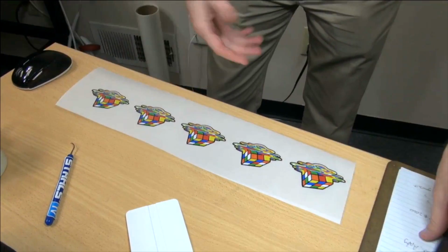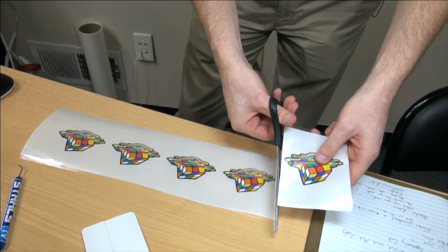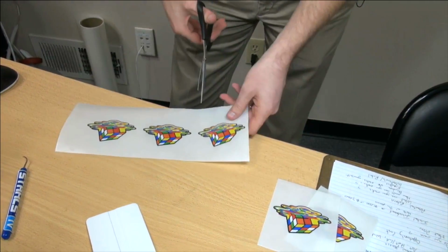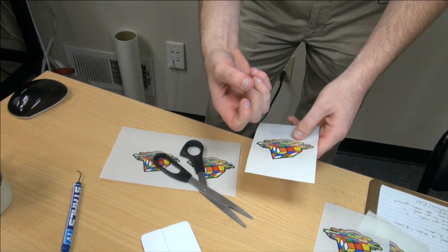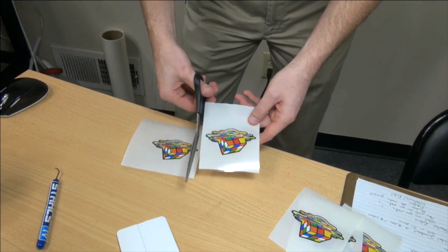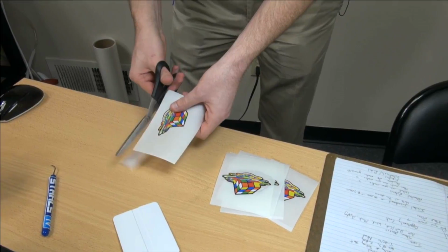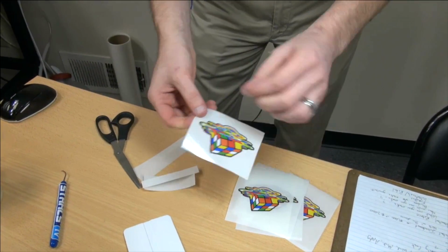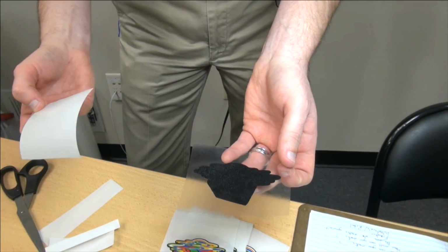All right, so now I can cut these apart. I can hang on to them for a few days if I want to use them later. Normally we get the question, how long can I let these sit? You don't want to leave them sit for weeks at a time, because what happens is the ink can actually migrate back into the mask, and the mask will lose its stickiness. So that's the risk of letting them sit for long periods of time. They can definitely sit for a week, 2, maybe even 3 weeks, but you probably wouldn't want to let them sit for any longer than a month. All right, so I'm just making this a little easier to grab, and then again, all we're doing is peeling off the backing, and we're ready to go to the heat press, which we already did.